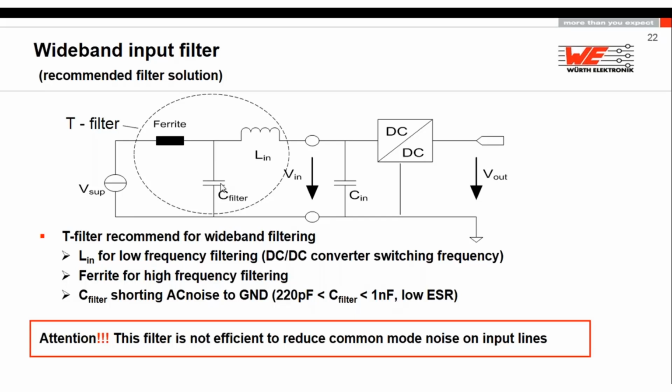In this area, if you put a 100 ohm, maximum 300 ohm ferrite bead, you will be much happier, because with less layer capacitance you will automatically have a much better bandwidth. You will cover much more frequency and the efficiency will be good enough. A 2 kilo ohm makes no sense because it has 2 kilo ohm but a very narrow bandwidth. All that is only because of differential mode noise.